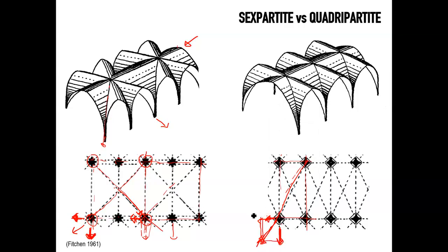And it would be less than the one developed by an equivalent square bay. So if I had here an equivalent square bay, it would be like this. This would require a 45 degree thrust that would have two components of equal size. But if I reduce it along this length, then I have halved the amount of side thrust that will have to be balanced by the next bay.